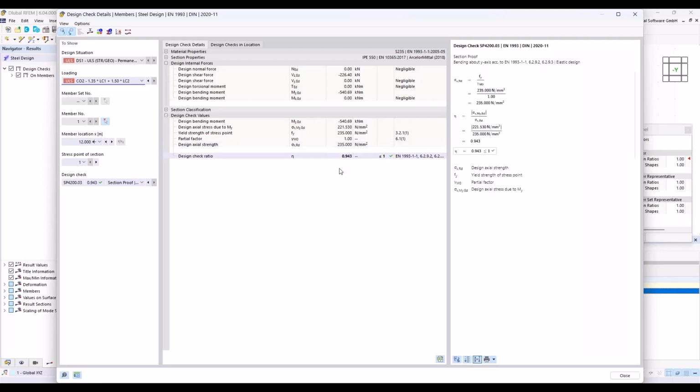Yeah, so we have now learned how to carry out a cross-section check and how to take the elastic and plastic design into account. At first the plastic design, in the second step the elastic design, because elastic design is allowed for all cross sections. And in addition, we now know how to display the design formulas and compare them with our own manual calculation.